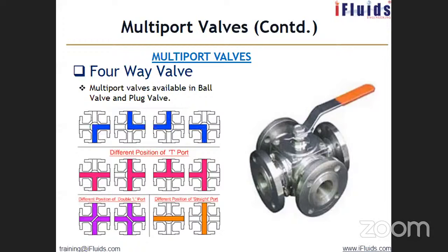Once the catalyst inside the absorber is saturated, no more water can be absorbed, then you isolate the vessel and divert the airflow to the parallel vessel which has fresh catalyst. So when that is doing the job of adsorption, you can regenerate the already saturated catalyst with hot air. So two flows can happen, and you can divert the flows to the desired vessels.